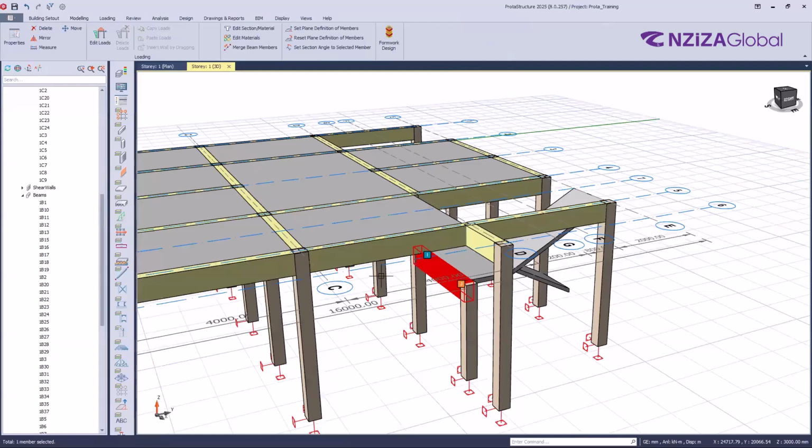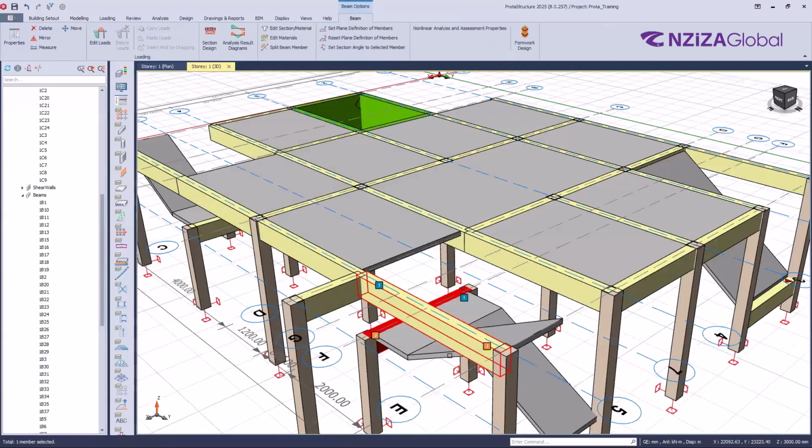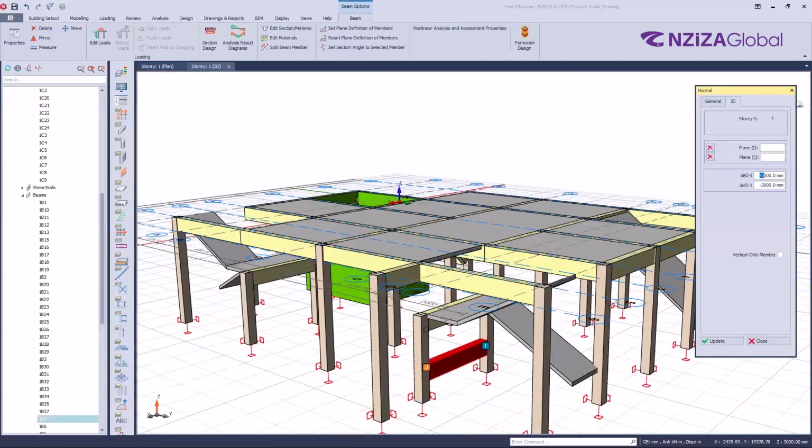So what you can do, you can just take the beam command like this and create another beam here. Sorry. So it has gone all the way down. So I can open the property, make sure the offset is none here, update. Okay. So now you'll have one beam here at the top. You'll have another one which is taking the landing here. That's how you can achieve that.